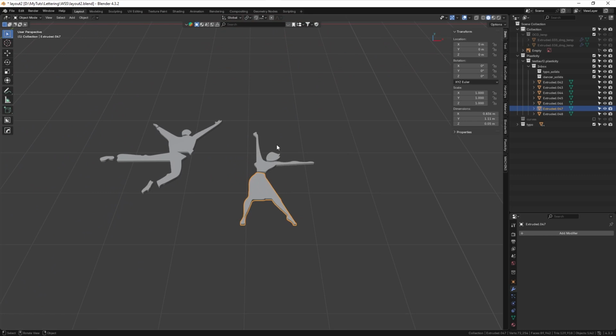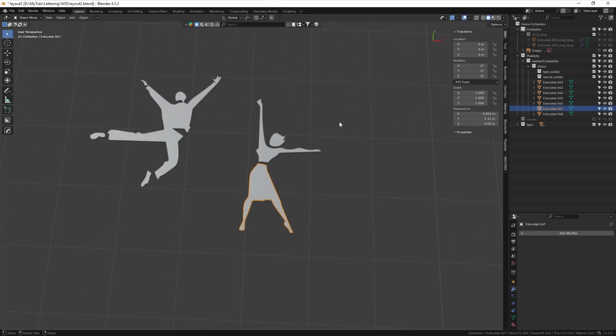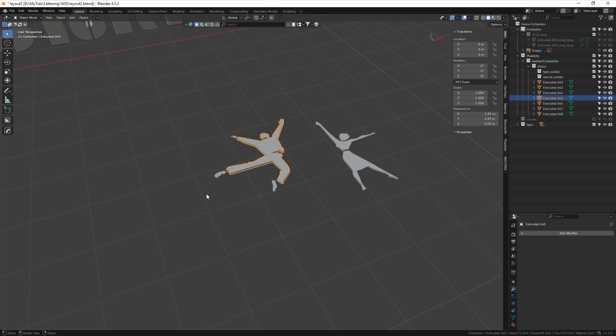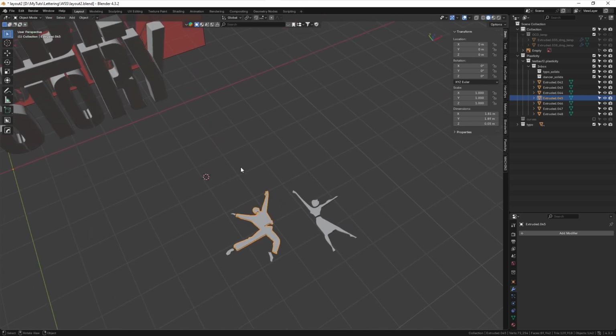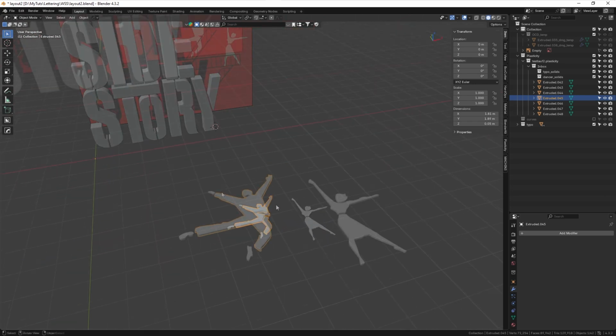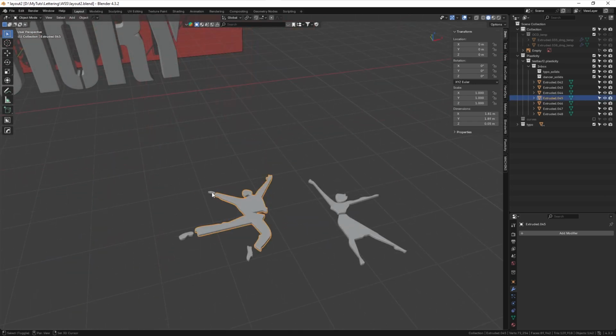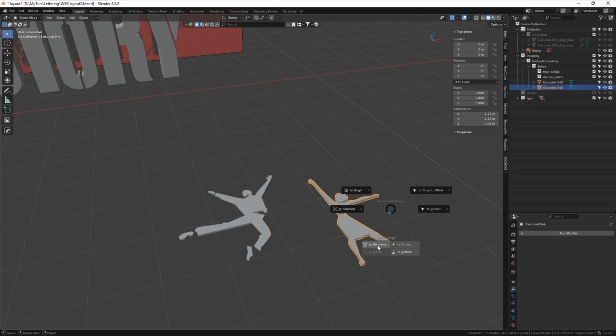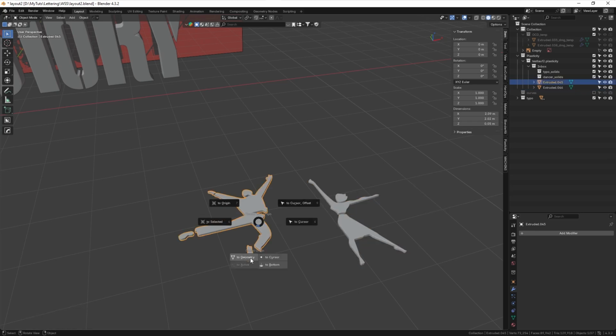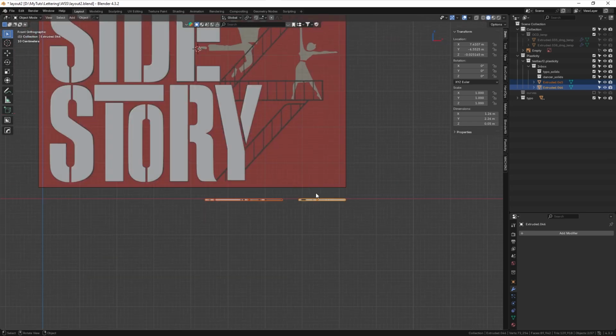And here in Blender we can group them, we can join them, so the scene isn't that cluttered. Any further editing or modeling in Blender isn't necessary. We just need to position them according to the design. So therefore, let's first join them. Select all four parts of the male character. Ctrl J. Do the same for the female. Ctrl J. Shift S to geometry. Here also Shift S to geometry. Let's select both of them. Let's look from the front view.